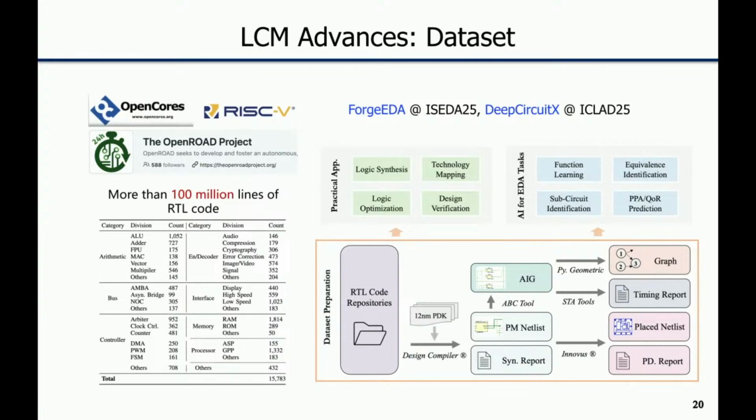And then secondly, if you think about hardware design, there's a unique benefit for learning: we are not going to implement everything in hardware, right? So the number of possible types of chips is limited. You have all kinds of processors, all kinds of communication chips, and so on and so forth. It's actually a limited set, right? If you go one step further, let's say digital chips, they are all composed of data path and control path, right? The data path is all sorts of multipliers, systolic arrays, all these things, and the control path is all kinds of decoders and muxes, whatever it is, right?